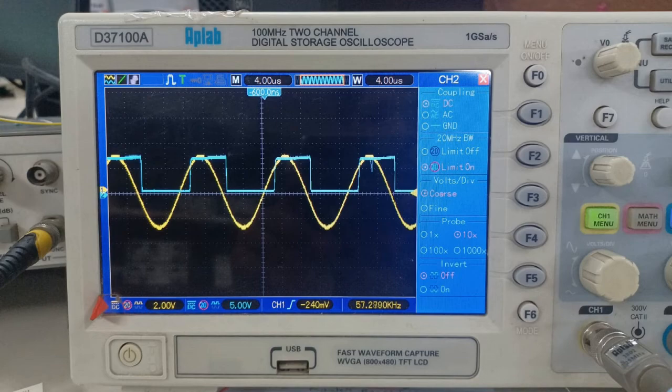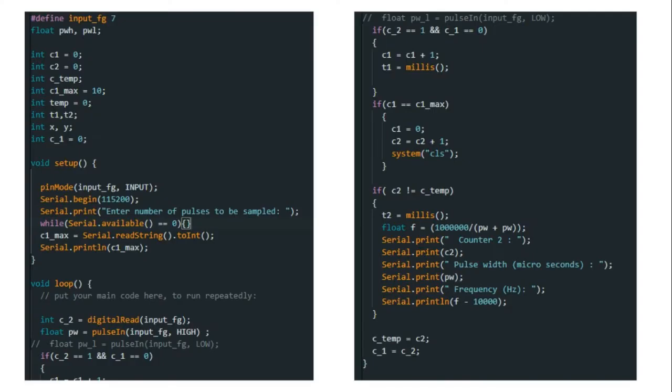In the second part of our project, we have done the counting part of our code in NodeMCU v3 after upgrading it from Arduino Uno because of its better CPU clock frequency of 80 MHz in comparison with Arduino's 16 MHz. We are still researching on microcontrollers offering better clock frequencies which are also affordable for us as students.